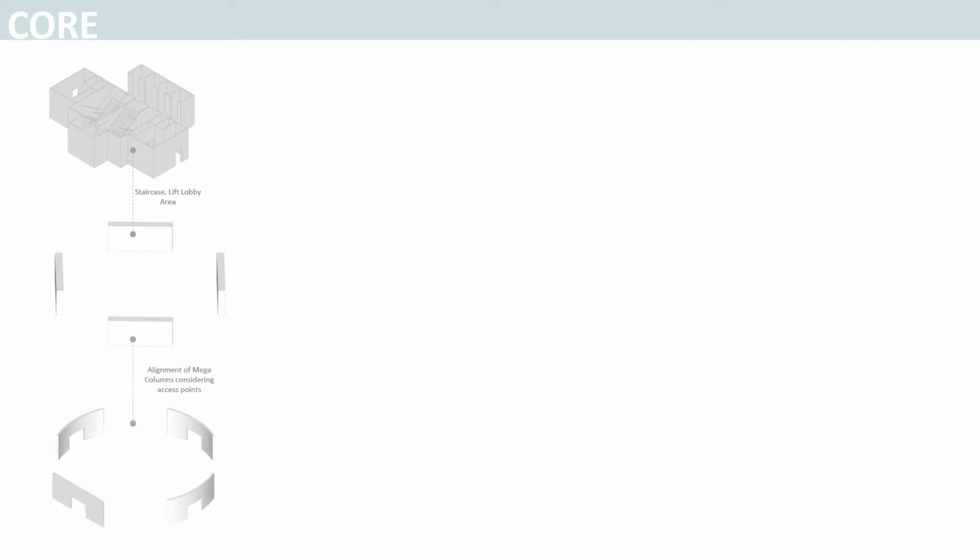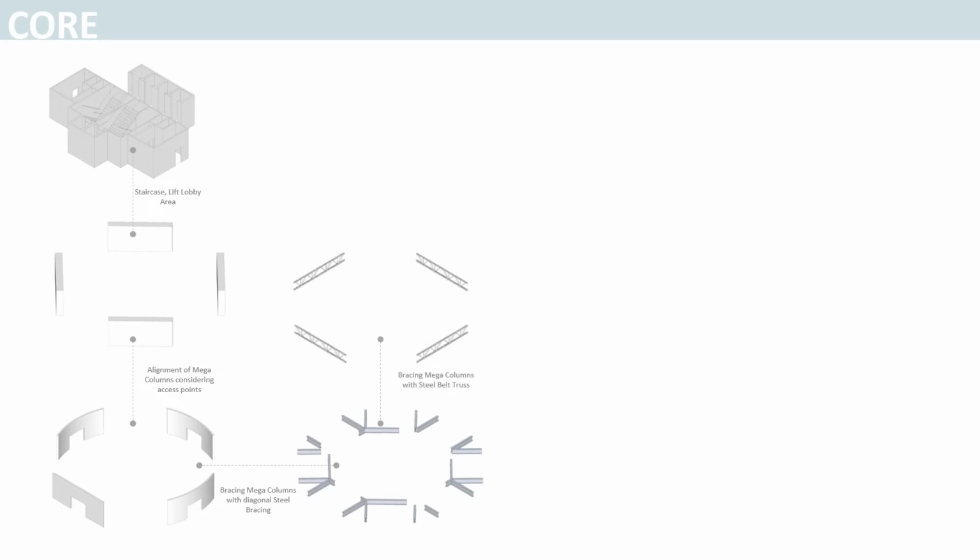Moving on to the design of the central core of the building, the requirements that we have looked at are as follows: rigidity to the core. 1. Concrete shear wall, lift and staircase walls. 2. Concrete mega columns. 3. Mega columns anchored to each other by outrigger beams and belt truss of steel. 4. Provide additional rigidity, introducing bracing members as diagonals of steel. 5. Anchoring the external function branches by radial trusses of steel.